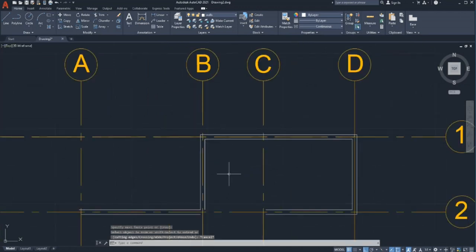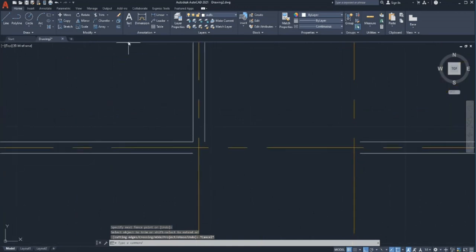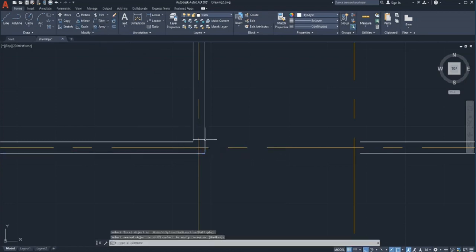Another way to do it is by holding the line and then decreasing its length using those blue dotted anchor points. Some people call them extension points. It does not matter as far as the purpose is being served. Another approach to do the same could have been the use of rectangles, since we know the height and the total width of the rectangle. It is quite an easy task.